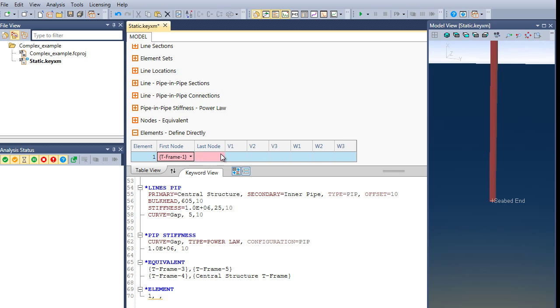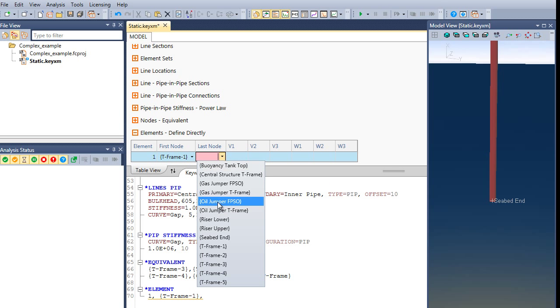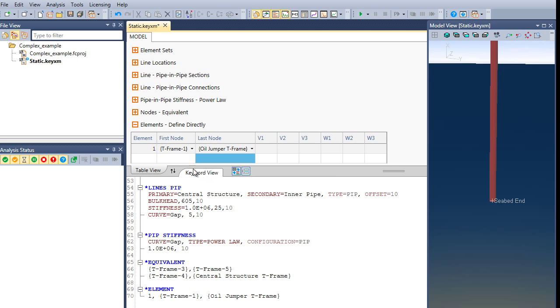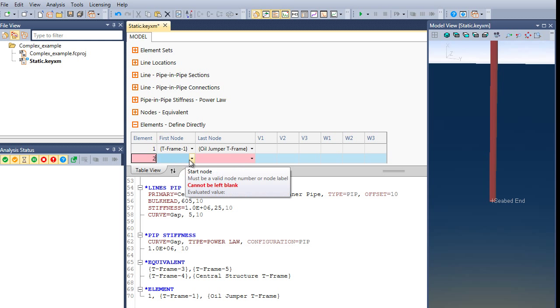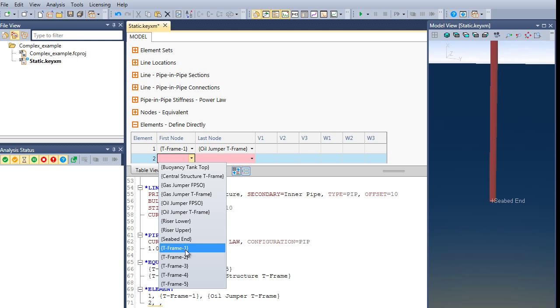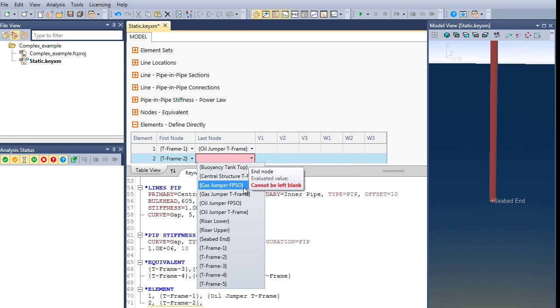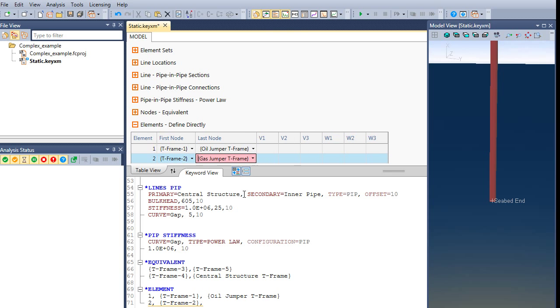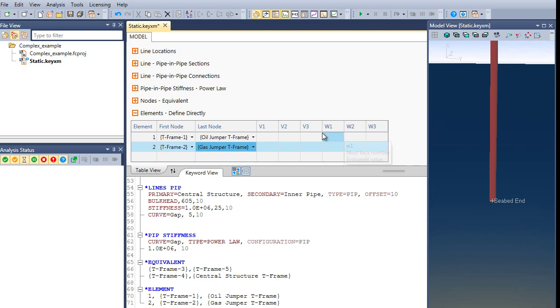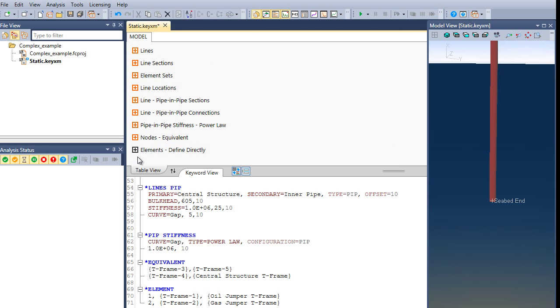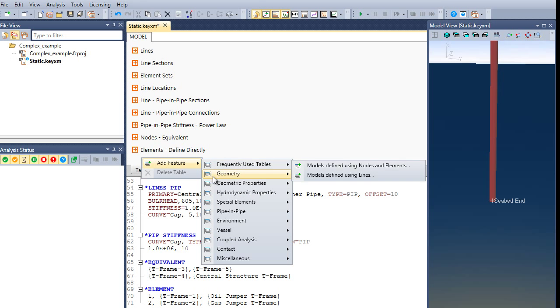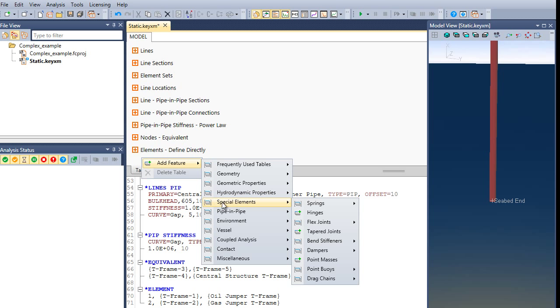Nodes and elements represent the most basic building blocks of a finite element model. Nodes represent the cornerstones of the finite element solution, while elements are used to define the finite element mesh connectivity. In some respects, the line modeling feature has rendered explicit element generation redundant to some degree, but the star element keyword is still retained in Flexcom for complete generality of model building.